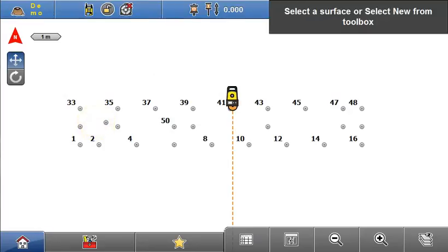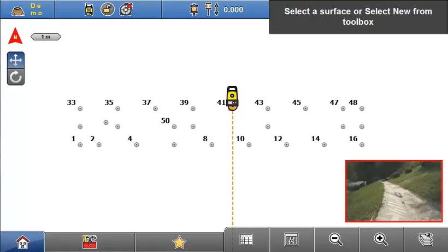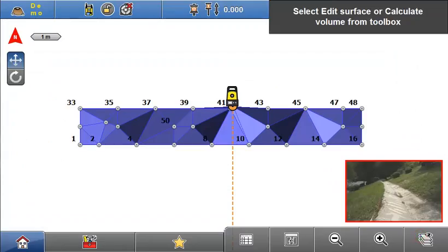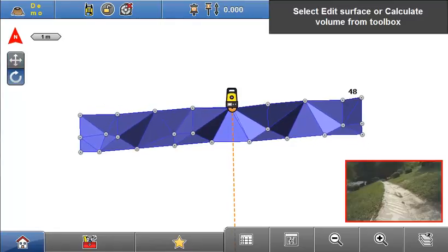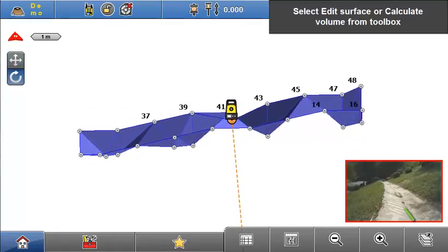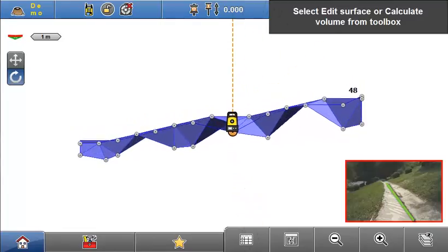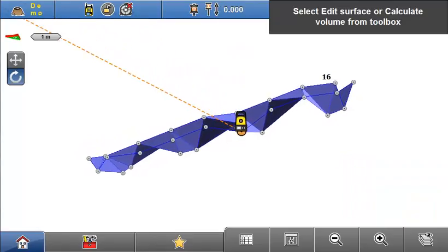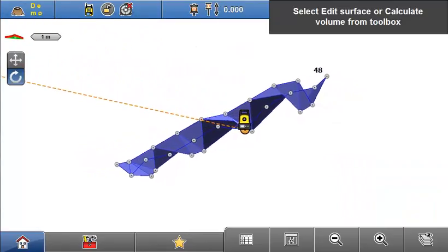What we can see here is a different data set that is an as-built survey of a concrete ditch measured by individual points and a surface automatically created out of those points. In order to precisely define a surface, as it is in the real world, it is necessary to add a break line. In this case, it will be the bed level of the ditch. This is necessary to achieve the correct processing of the 3D model.